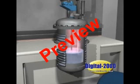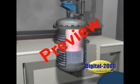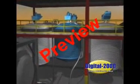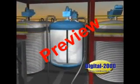This third test produced significant heat, but the water cooling jacket around the small vessel was able to keep the temperature low and control the reaction. However, MFG did not realize that compared to the small test reactor, it would be far more difficult to control the temperature in the 4,000-gallon production vessel. The surface area to volume ratio was much lower in the production vessel than in the test reactor.